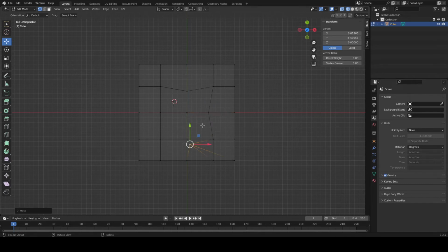As you can see, I just randomly clicked a vertex there, so I'm going to Control Z to get out of that, and I'm going to go back. I'm going to box select that collection of vertices here, and I'm going to set that to -4.5. Enter. There we go. And select these vertices here and -4.5.